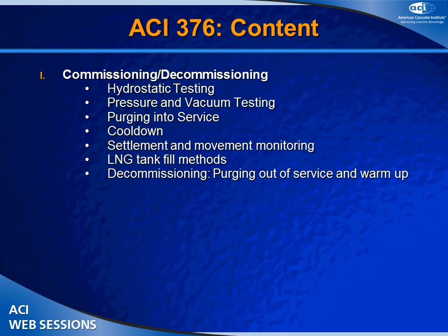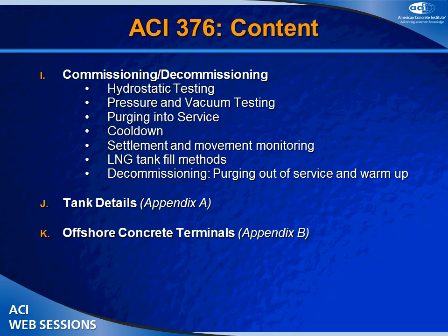And then commissioning. This is a little bit unusual too, because this is actually startup and in some ways maintenance of your facility. You can see here the fill methods, decommissioning, the cool down, getting ready for introducing the low temperature liquids. A lot of things that are really unique to LNG tanks. And then we have an appendix that has some of the details, so you can see this is what it looks like generally. We do have an appendix that deals with offshore concrete terminals, so we'll be developing a little bit more on that in our next revision.